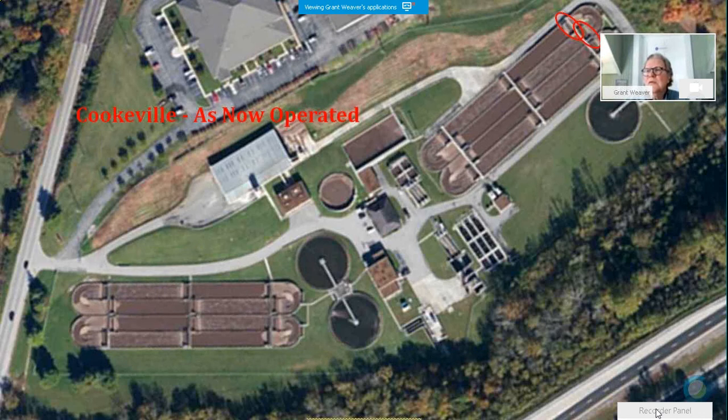So they now run with 2 rotors for a period of 4 hours. Okay, 2 rotors at each of the 4 ditches. So that creates a strongly aerobic zone immediately downstream of those rotors. It creates kind of a dead zone in advance of those rotors. And in between, a strongly anoxic zone. And then 2 more rotors for the next 4 hours. Now this sludge blanket, so they believe, and I believe with them, kind of moves around the bottom with all of this.